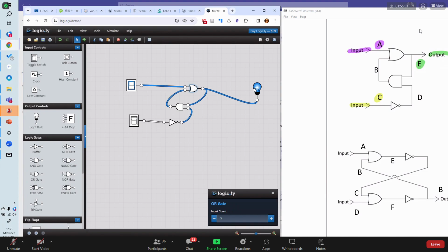If the input is 1, the output is 1. And due to that feedback loop from the output again to the input, which is an OR, which has the negated reset input in the AND gate, it is staying 1 because the output is 1 and the reset is false. Therefore, you have a 1 here as well. So now this loop is keeping the lamp alive. If you're now resetting here, then you will have a 0 and the AND will become 0.